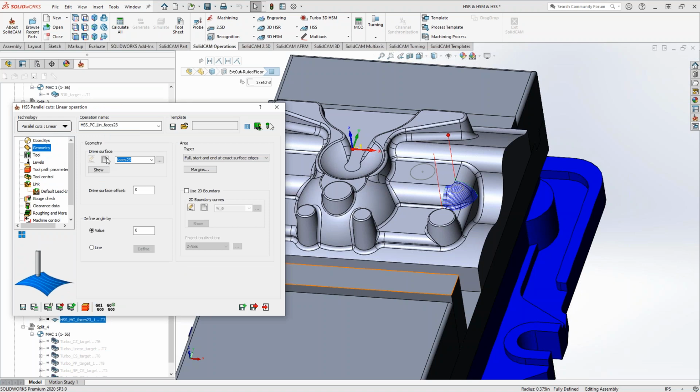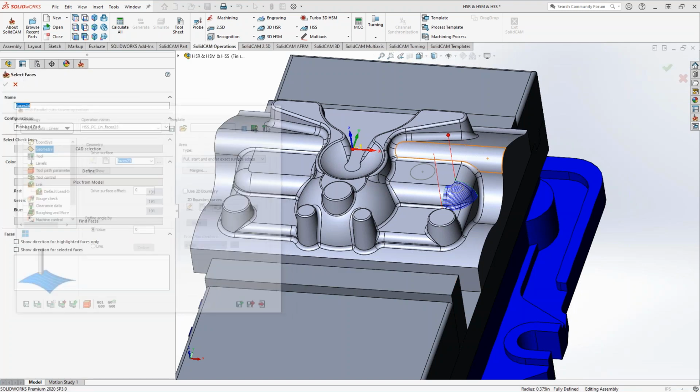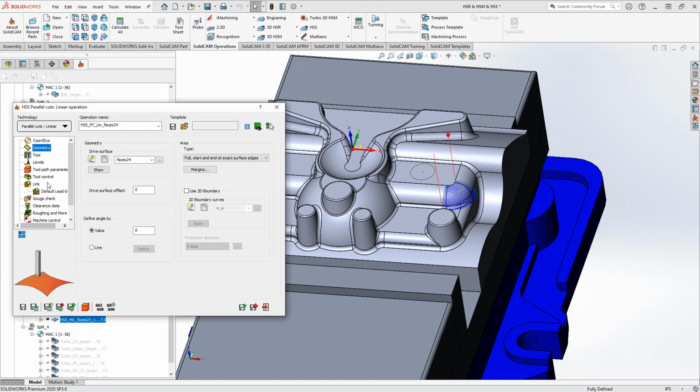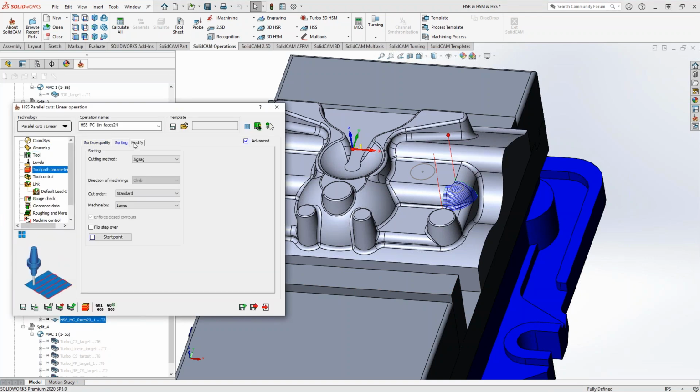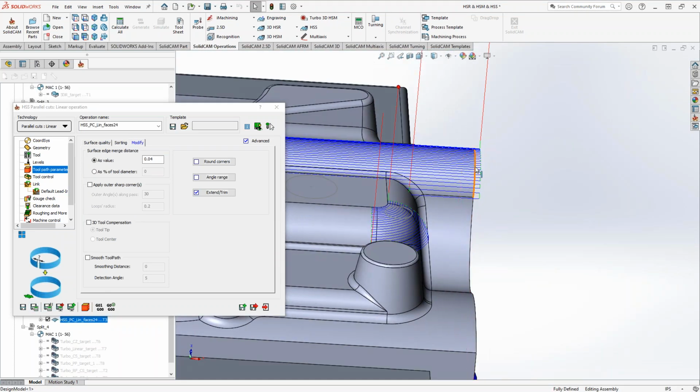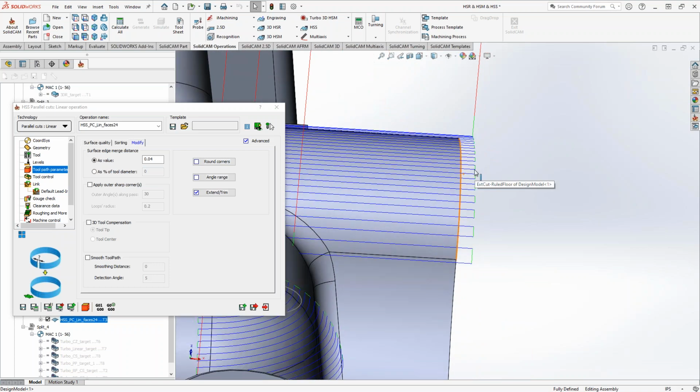And this really helps out with blending lines, or maybe blending two different toolpaths together to have a little bit of overlap right there. So a great feature in there, and anytime you're trying to extend something out, it won't drop straight down. It will just basically do like if you were to do a surface extension on that specific face of that model.